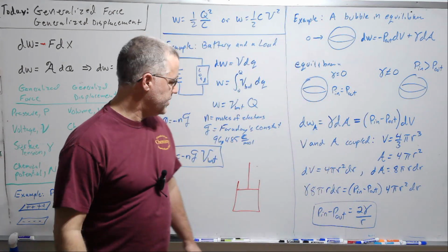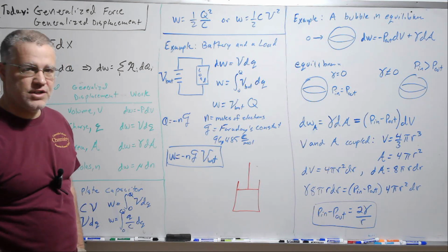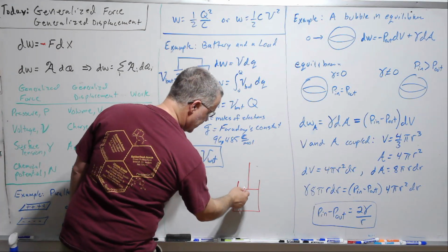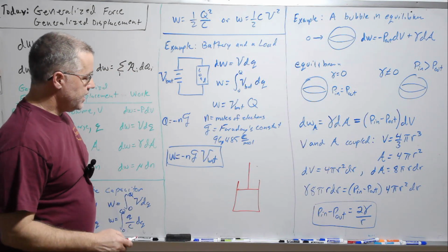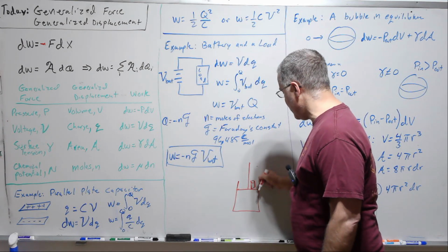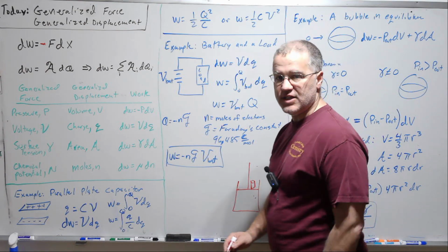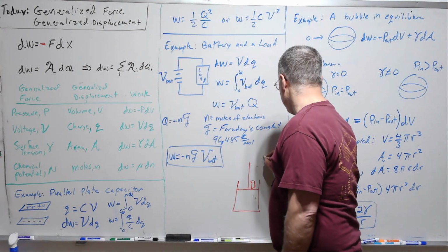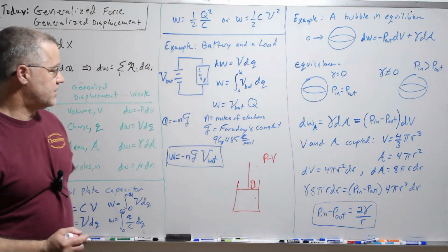We'll talk a little bit about pistons in this course, but later in the curriculum, after these introductory courses, pistons will be used a lot. And so if we think about what a piston can do, that's this container with one single arm that can slide up and down. And you can trace this back then by, say, you put a mass on here and that'll apply a force. But what's really happening is you're changing the volume against an external pressure. So this is a pressure-volume system rather than a force-displacement system.